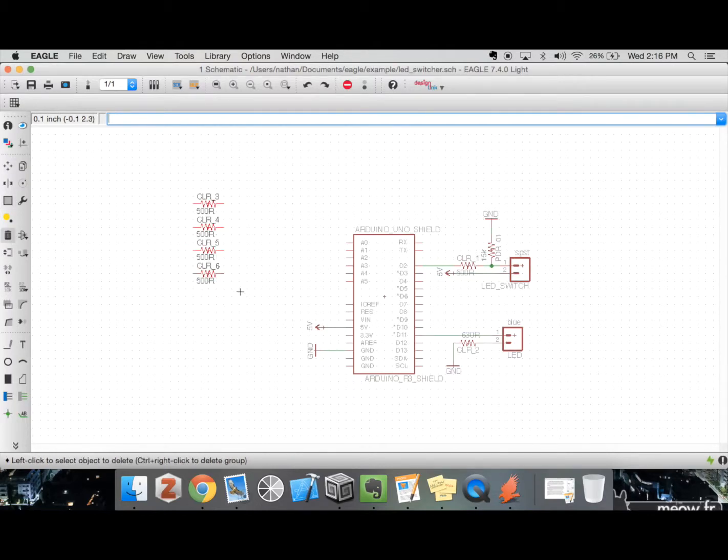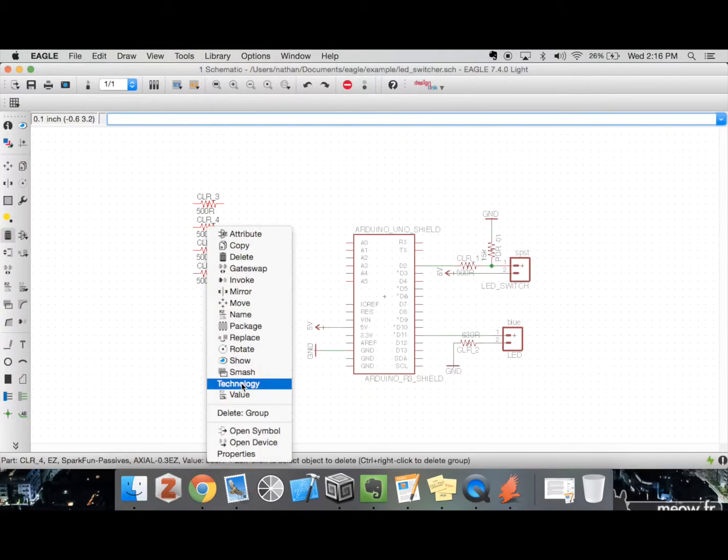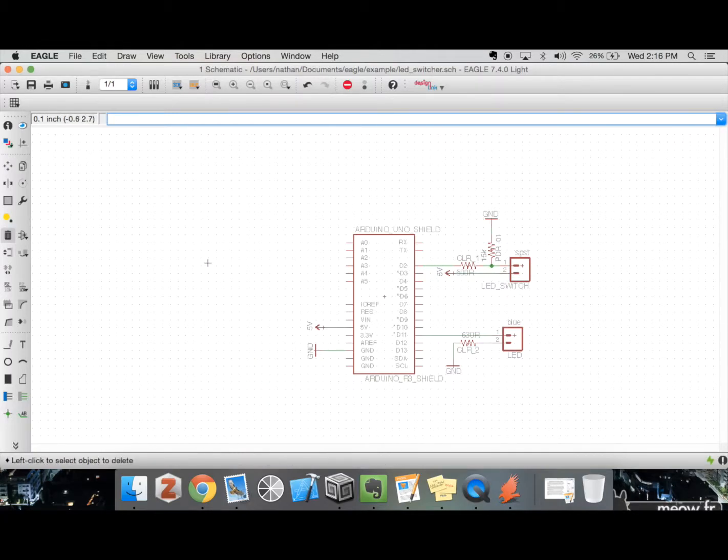So I select group again, I'm going to right-click, and the best is towards the center but not on them. But let's say I did it on, then I still get access to this one and only operation that I can perform on the group. So if I click delete group, then I can delete the group. And the reason why I defaulted back to delete is because that was a tool that I used before group.